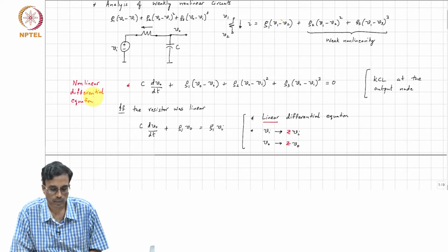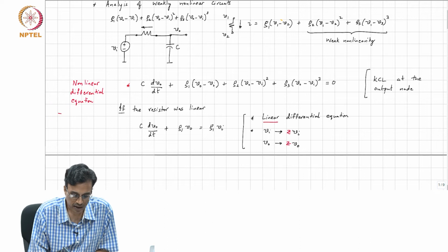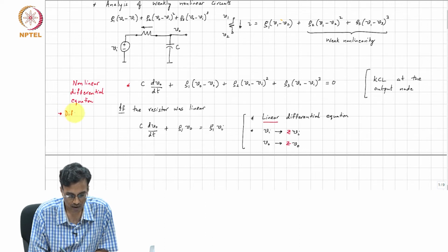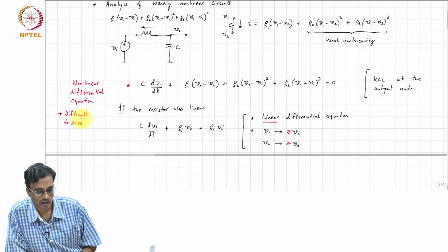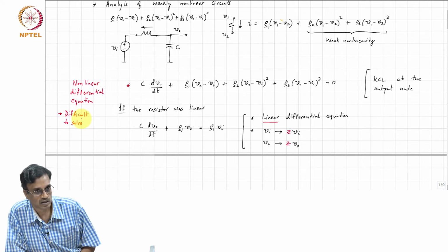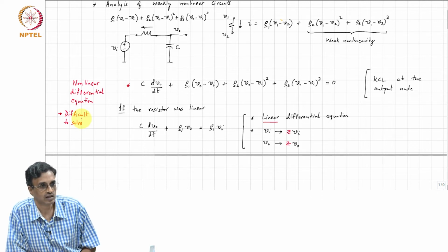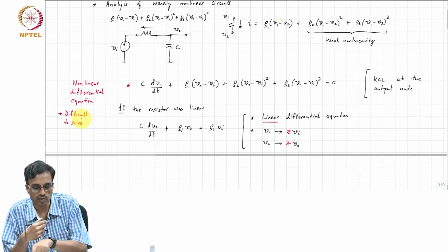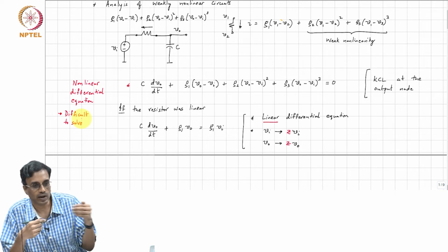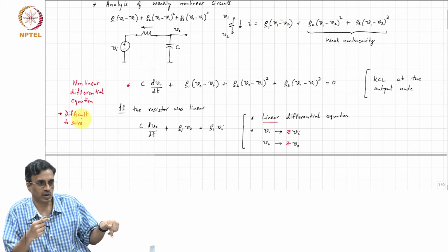Right, and in general nonlinear differential equations are difficult to solve. You might argue that here maybe we can, but more importantly, when you have a more complicated network, you now not only have nonlinear differential equations at every node, because the KCL KVL equations now become nonlinear differential equations, and they are all coupled, correct, because the Vo of this node is going to be in one equation, then it is going to appear in some other equation, right.